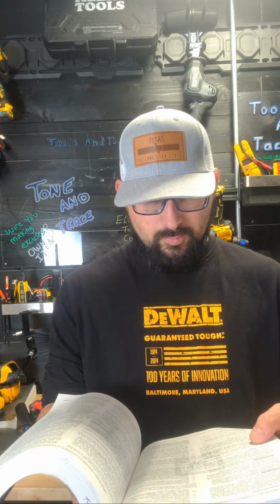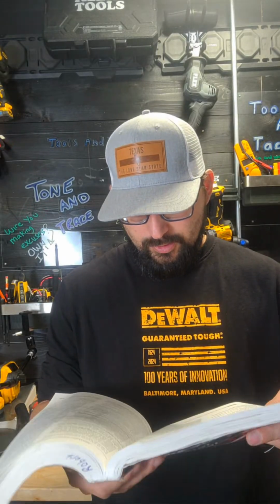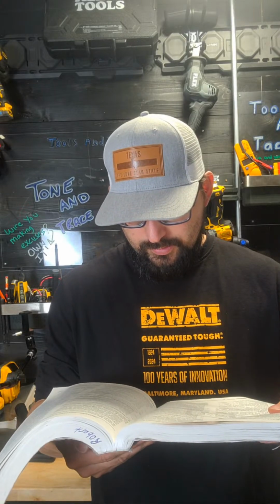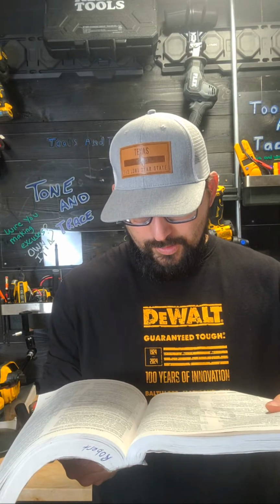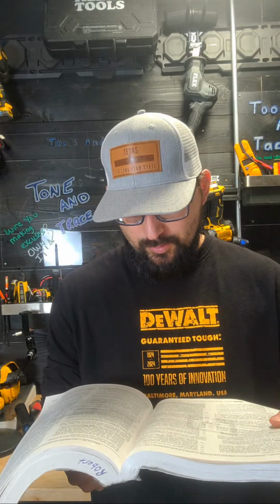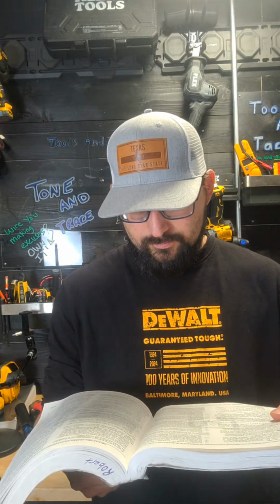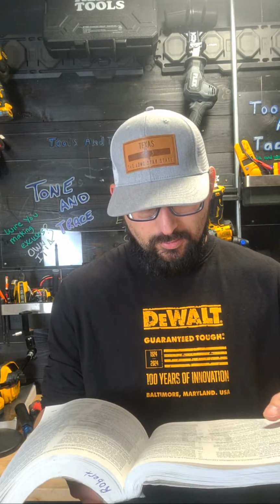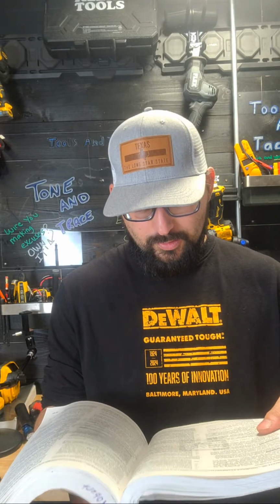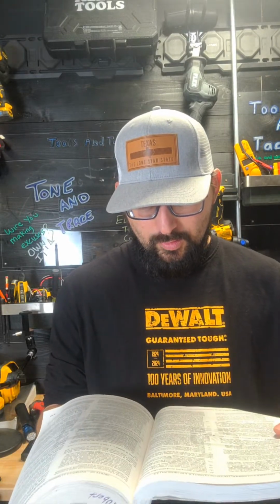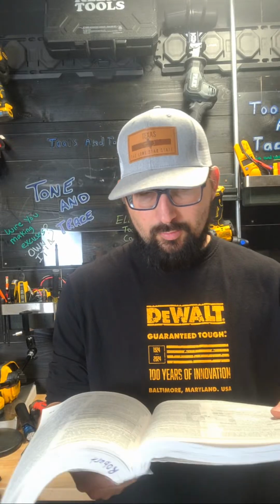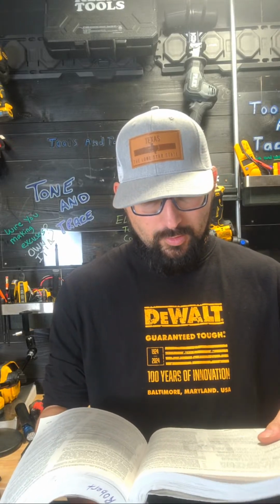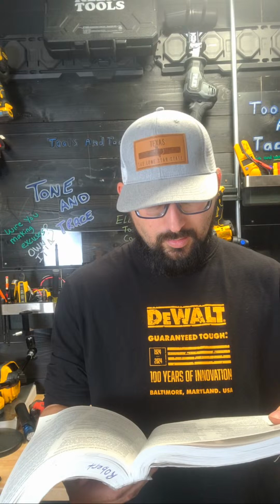So a Division 1 would be normal operation conditions. A Division 2 is going to be in case of accidental rupture or breakdown. So you've got Class 1, Division 1, and Class 1, Division 2. Division 2 is accidental breakdown or accidental rupture. Class 1, Division 1 is going to be normal operation.